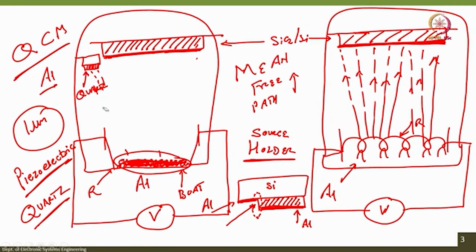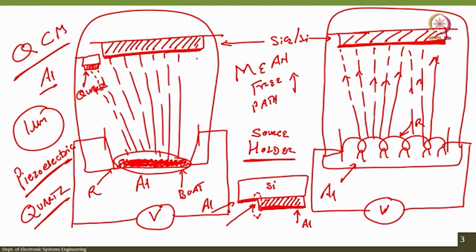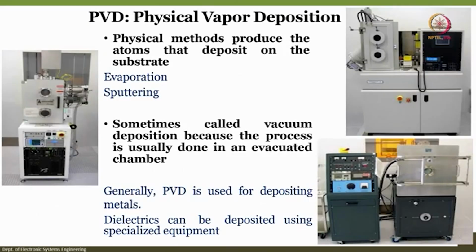So, you wait till the metal gets melted and then you open the masking plate, right. So that when you start deposition, it will be uniformly deposited, and you can always close the deposition not by just dropping the voltage, but by bringing the plate back into this direction. If you bring the plate back, the material that gets deposited will not reach this region, correct. So, that is how things are done. So, let us see the slide.